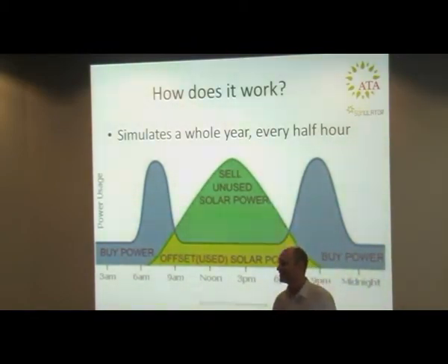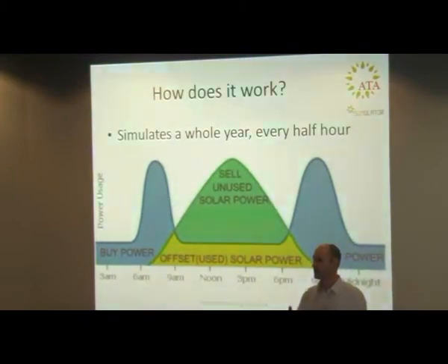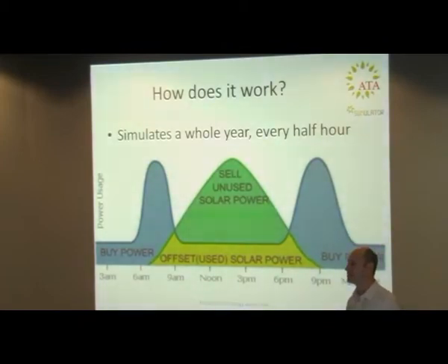So your panels are on the east and west instead of the north. Yep. And that's something you can use Sunulator to model, to see what the impact is. I haven't got a slide on where you input the solar panel data, but you can put in 2 separate arrays. You can say there's only one and it's all north facing and it's 3 kilowatts, 30 degree tilt. Or you can say, we're going to put half of it east at 30 degree tilt, let's say 2 kilowatts east and 2 kilowatts west. It'll calculate the generation from the east array and the west array separately, and then add them up. So you can see what the impact is on the payback.